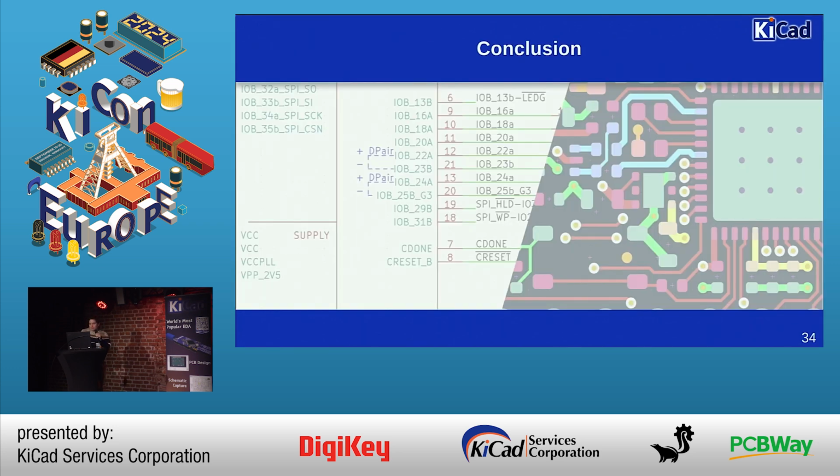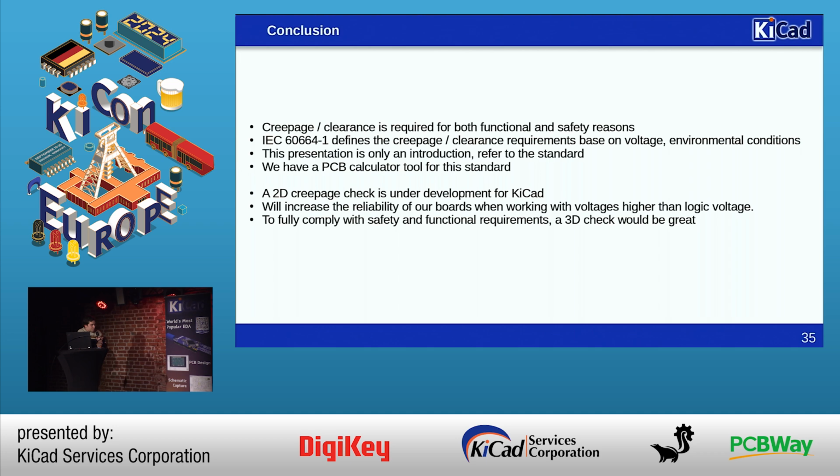As a conclusion, because this is the end of my presentation, clearance and creepage are not only for safety. It is for safety, but it's also for functional reasons. As I said, if you have arcing and leakage currents everywhere in your board, bad things are going to happen, may it be a wrong sensor output or something. Things can happen. And so the IEC 60664-1 defines the creepage and clearance requirements based on voltage and some environmental conditions.